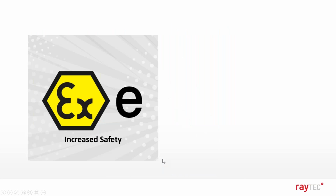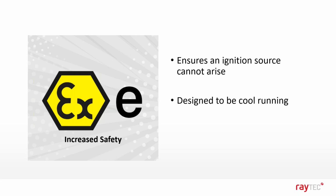So let's move on to the protection methods now, and we will start with EXE. This is officially known as increased safety, so that may be more familiar. The EXE protection method focuses on preventing rather than containing an explosion, by ensuring an ignition source, i.e. a spark, does not or cannot arise. To do this, the luminaire is designed to be cool running.